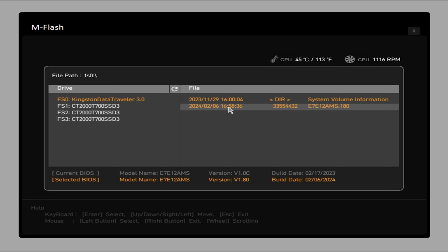There's not too much else to go in here other than the step up time, which is basically how quickly the fans will move up and down. So if your CPU temperature is fluctuating quite a lot, you don't really want your fan speed to be flying around all over the place, because it will just generate a lot more noise. The tone of the fan will be changing quite a bit over time. You don't really want that. You just want your fan speed to sit as it is, and having it switching back and forwards all the time isn't going to do your cooling any benefits either. So if you increase the fan step up time, that will slow that curve, give it more of a curve, and it will just gently ramp up fan speeds. So that's a pretty cool thing.